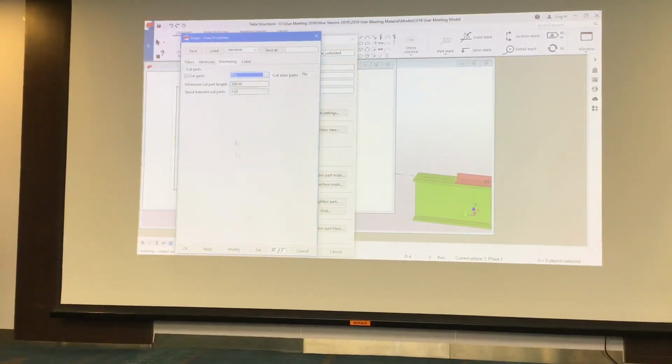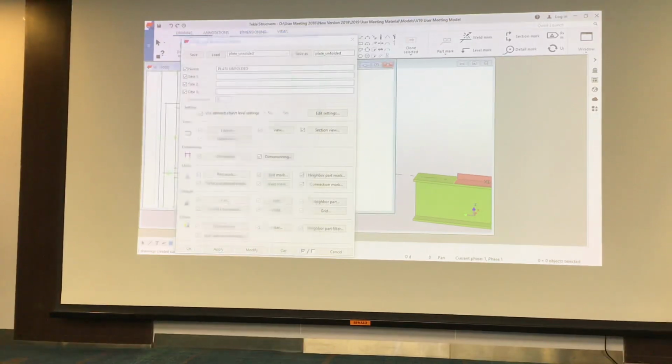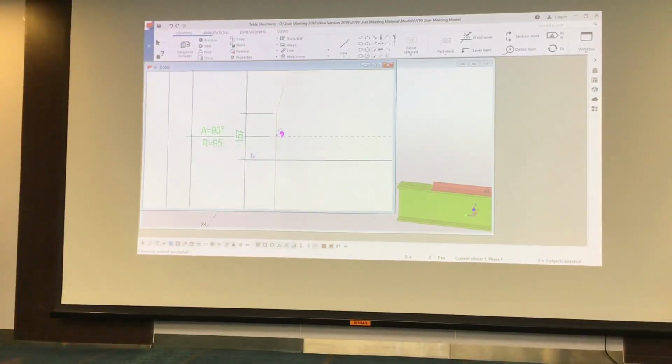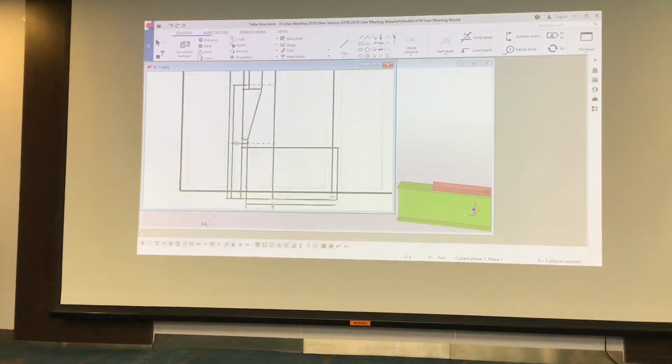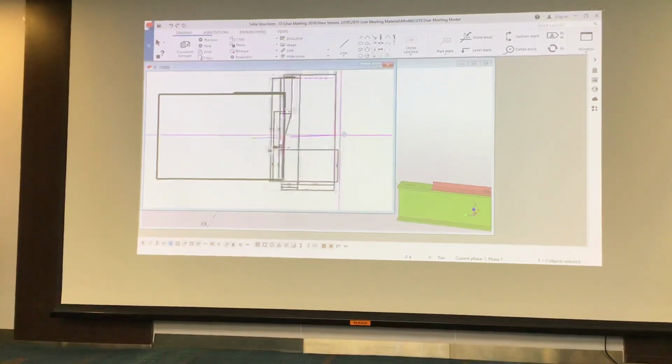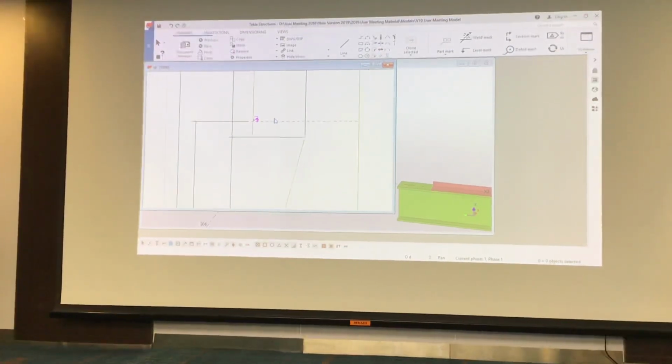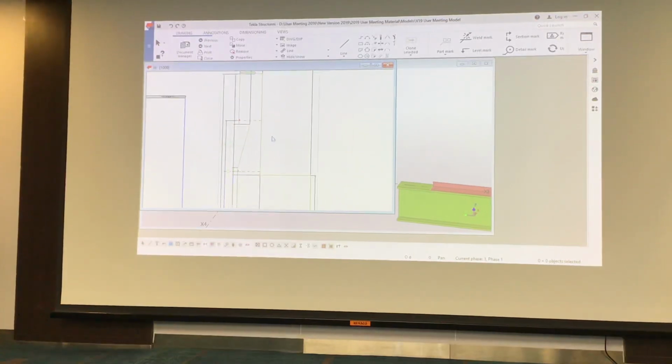Shortening is none. Just so you can see, look, then what you get here is you get the unfolded look with the angle, showing how it's unfolded. Just move this out so it's not in the way, move it over here. So you can see, look, then, all the unfold lines, the bends, everything like so. So that's a proper unfolded piece of that plate.